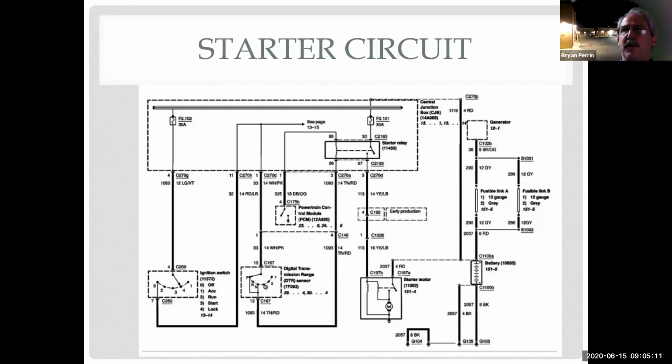Because if I go to the relay first and I don't have any power right here coming down, doesn't that tell me to go check the fuse? But if I check the fuse first, then what? I'm going to check this fuse next, and then I got to go to the next thing. But if I go to the relay, it's central. I can kind of figure out where I need to go.